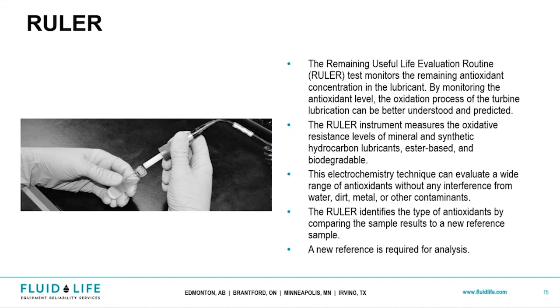And it means knowing the condition-based parameters instead of just time-based parameters, which I think everybody's moving to in wind, especially because it's the hot thing. Whether that's looking at your vibration data, temp data, or infrared or anything else, right? This is all taken in conjunction with one another.